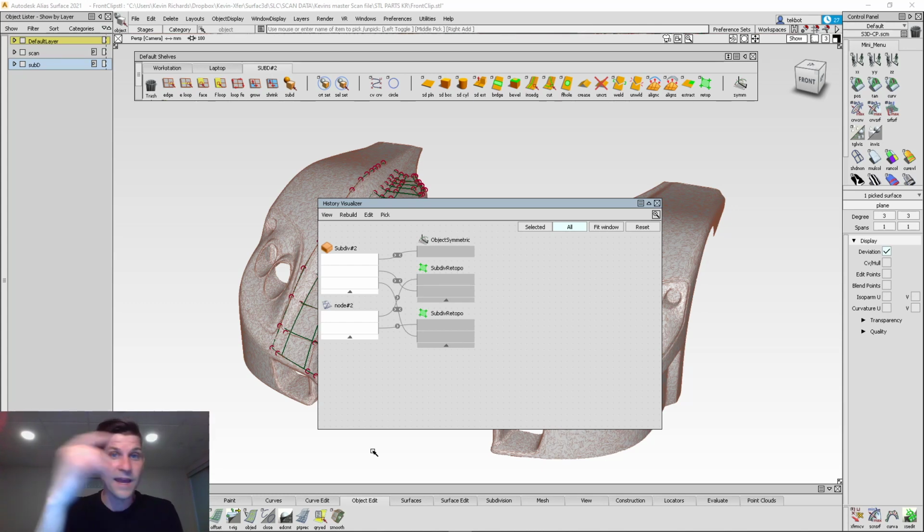You can just reconnect what curves a bi-rail is creating or built from. Or maybe you select a curve by accident instead of selecting a surface edge, so you're not able to get a continuity. Just switch it. Switch to the edge. Unconnect the curve, reconnect the surface.